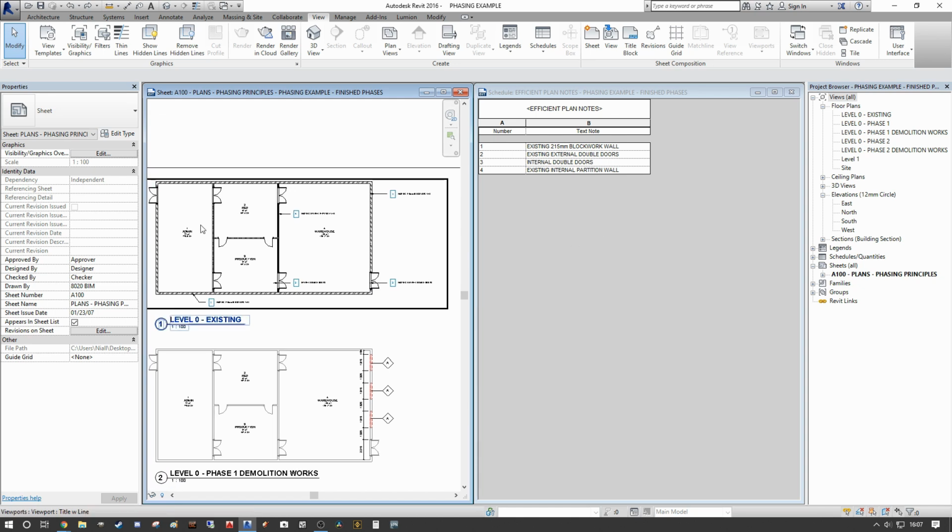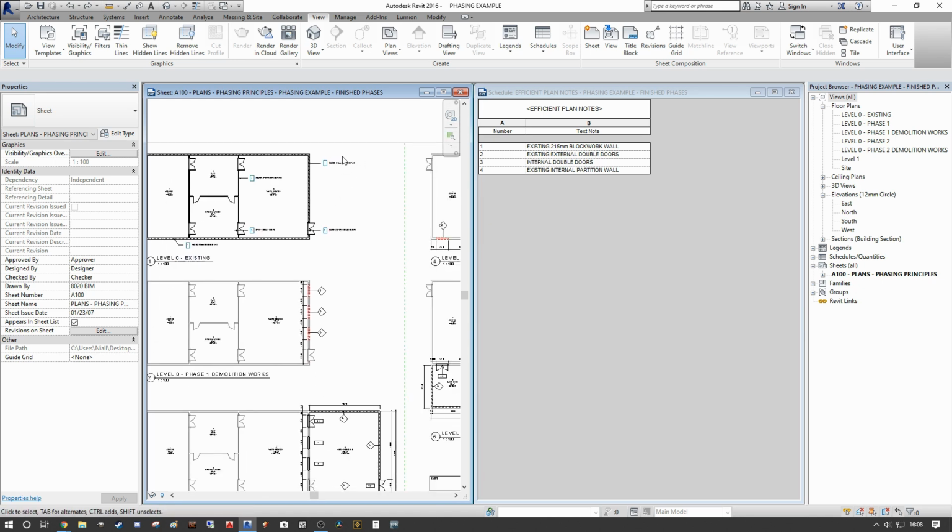So this is brilliant. We have a first pass of our schedule here, and we have one view specific with our text notes on it. But the real power becomes when these text notes apply across multiple views and we can edit them all within the schedule in one fell swoop. So what we're going to do is give an example of that.